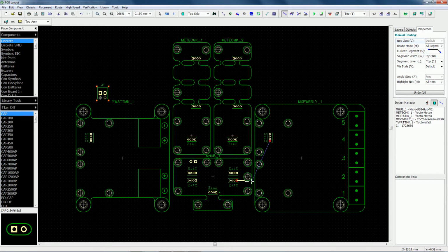And I'll have to avoid areas such as screws, because I don't want to create a shortcut when I place the screw to hold my devices. And I connect one pad to the other. There is an auto-routing function in this software, and you can try to play with it, but usually I don't like auto-routing a lot because it makes funny stuff with power connections going in all directions. So usually I prefer to do the routing.